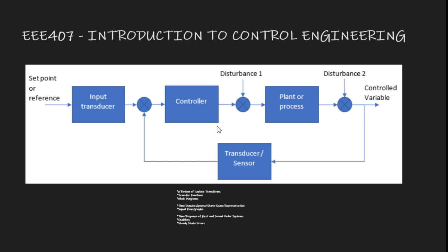In that system, we know that the value of the thermometer won't suddenly jump. You have to wait a little while to take a measurement. Now, how long should we wait? The time response of the system defines how long we have to wait before the instrument gets to its steady state, in other words, before the output of the instrument settles to a final value. When it has settled to a final value, we can now take our reading.